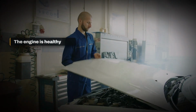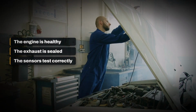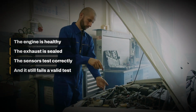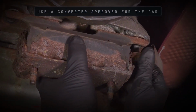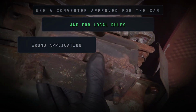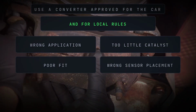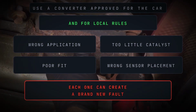When the engine is healthy, the exhaust is sealed, the sensors and circuits test correctly, and the catalyst repeatedly fails the manufacturer's valid performance test, replacement becomes justified. At that point, use a converter approved for the exact vehicle and local emissions requirements. A converter with the wrong application, insufficient catalyst material, poor fit, or incorrect sensor placement can create another fault even when the engine is healthy.